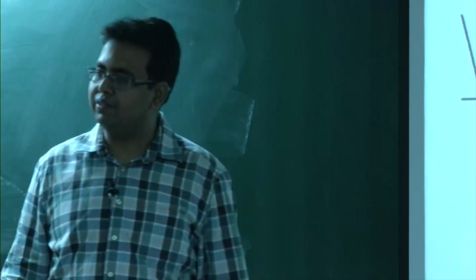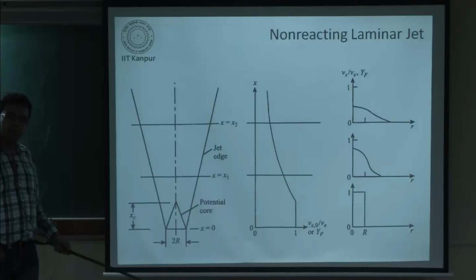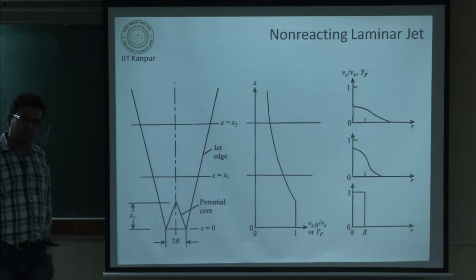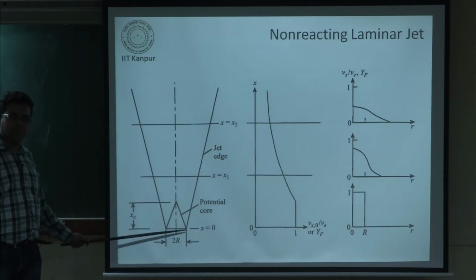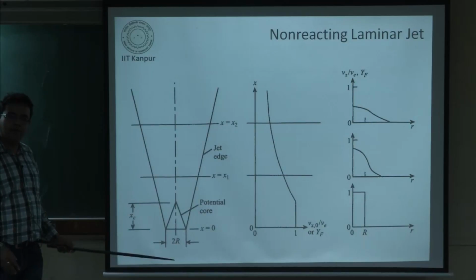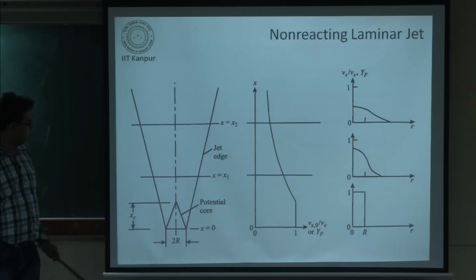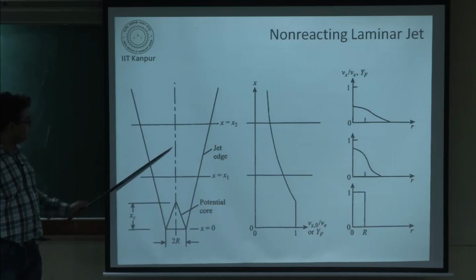There is no viscous effects, right. Okay. So, the potential core is where you do not have any viscous effects, and the flow is merely potential, and there is no change in the velocity within this region. Okay. So, the velocity from here to here will not change very much, the same as the concentrations that we are going to see. So, now what is happening, this jet is coming out and then it is spreading. Okay. So, this is represented by the jet edge.